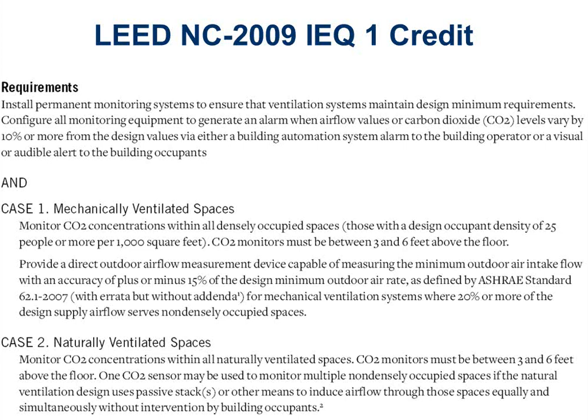And then the other thing that happens is on zone systems, we have to bring in the air to take care of the worst case zone. So that may cause some of the other zones to become over-ventilated as well. Now, when we're saying over-ventilated, we're not bringing in more air than the regular code would have said. We're still bringing in less than the regular code's outside air. We're just bringing in more than we actually have to with the CO2 system.